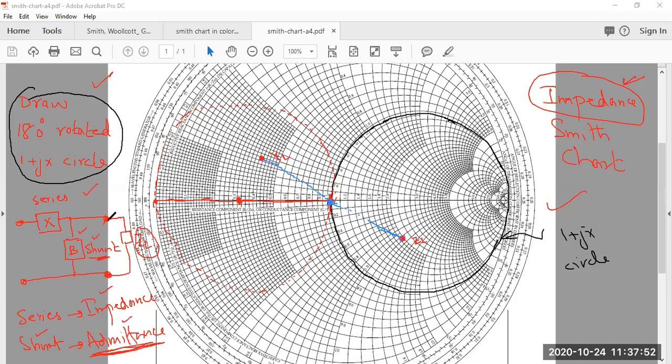Okay. So now, once this is admittance and this is already admittance, when you are representing these, this is admittance because Z is r plus jx, and Y is g plus jb. Whether you are talking about Y or B, B means it is susceptance, the imaginary part of admittance. Right now we don't know what B is. Keep this in mind: we don't know the value of B. We are actually interested in finding the values of B and X.